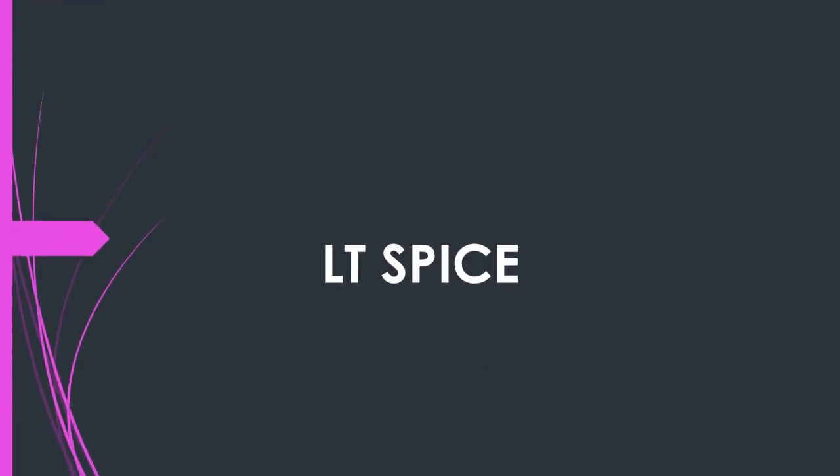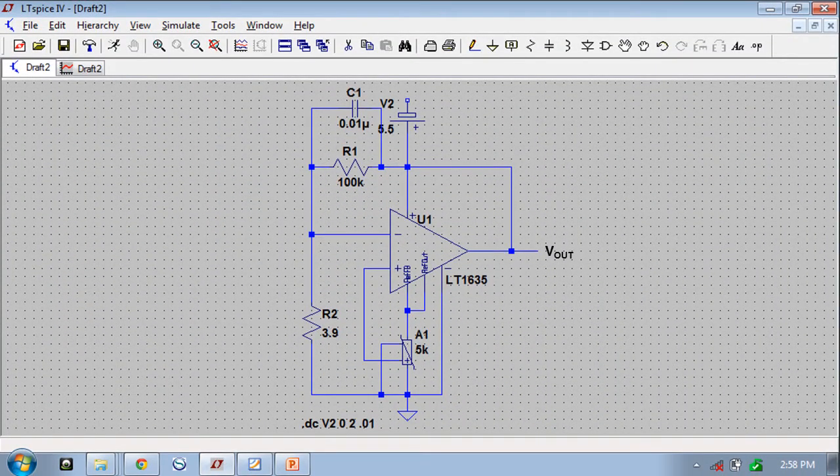For our LTspice example, we made use of the LT1635, which ensures an output voltage as low as 0.2 V for the reference voltage, referred to as V minus, and includes a buffer amplifier to enhance flexibility. The reference and buffer combine to achieve a drift of 30 ppm per degree Celsius, a line regulation of 20 ppm per volt, and a load regulation of 100 ppm per milliampere. It is connected to a 5.5 volt source, which is required based on the spec sheet.